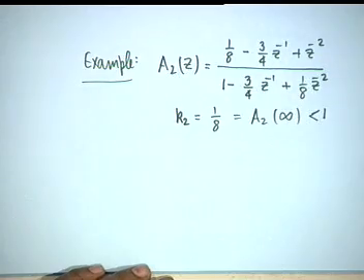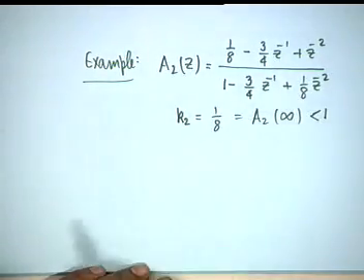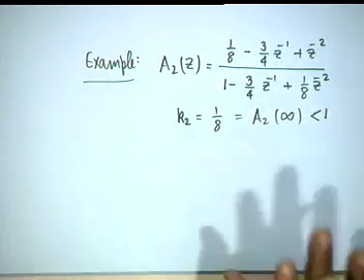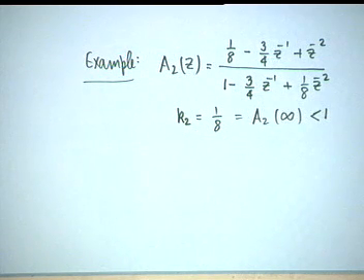I also told you that if at any intermediate stage any of the k's comes out equal to or greater than 1, your job is simplified. You do not proceed further because the system becomes unstable, and an unstable filter cannot realize any useful job unless you design it to be so. An oscillator is an unstable system, but your purpose is to generate sinusoidal or other kinds of waveforms.